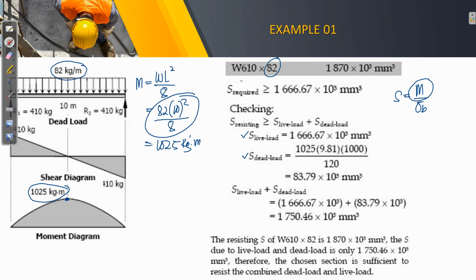So on that, we need to multiply it by 9.81 in order to become Newton. Okay. So we have already Newton here. But your distance is in terms of meter. Remember that. Okay. So we need to express that in terms of millimeter to jibe with the unit of the megapascal here.